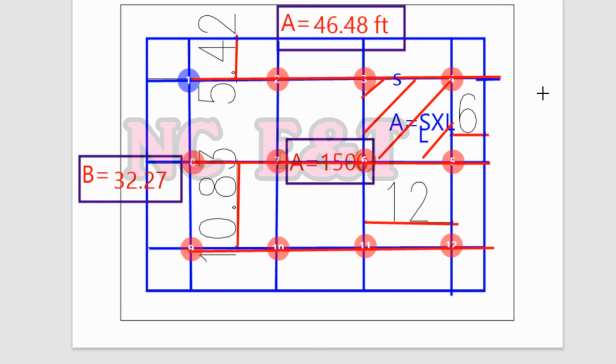And now in this way we have completed the study for the remote area, and we have the result. We already found the distance between the sprinkler and the wall on the same branch, and between the sprinkler and sprinkler on the same branch, and the distance between the sprinkler and the sprinkler on the adjacent branch. These values now we will transfer to our main project.